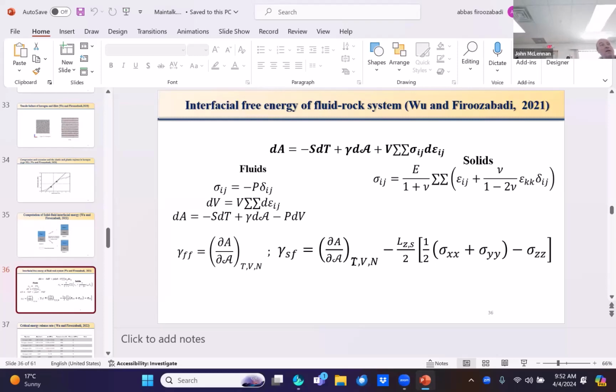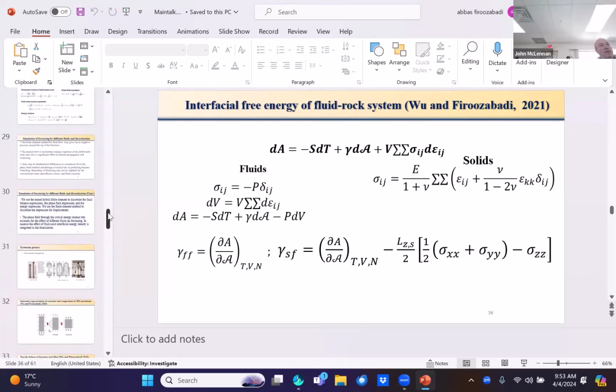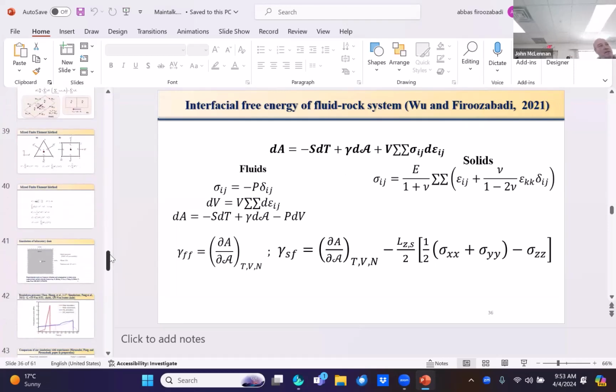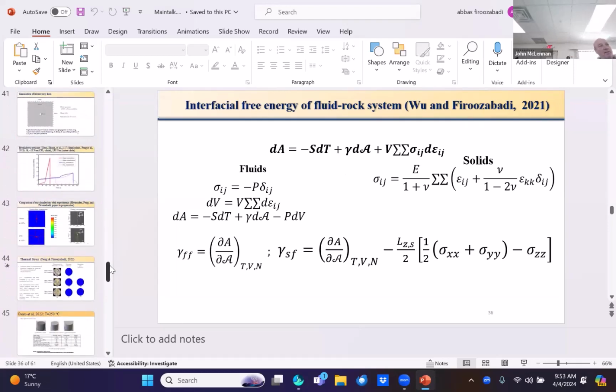So Yoshioka has another question, and that is for the water fracturing examples with different temperatures, 200C, 350C, 450C, where we're simulating the Watanabe 2017 experiment. Did the strain energy release rate dependency on the temperature change the fracture pattern? It did, actually. It did.